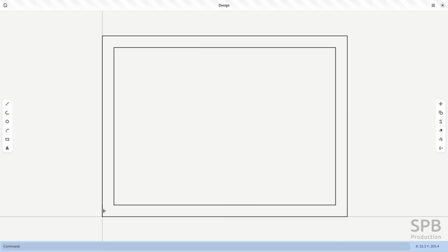And now if I want to select it again and move it again, I can either move my mouse like so, and then sometimes the line pops up, or I can use the box selection. So drag my mouse from left to right like so, and it selects the objects which are inside of the selection box. Now I will use again the move tool, click here, point my mouse in this direction and type in 1,500, and so this line is created.